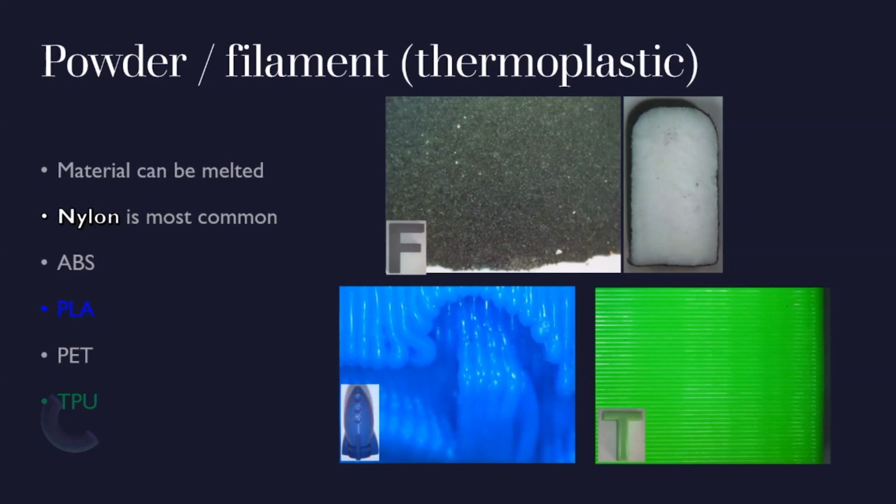Similar in process and properties to ABS is PLA, which is short for polylactic acid. Its key characteristics are that it is cheap, easy to print, and considered a renewable bioplastic that can be composted in high temperatures. However, long-term stability of the material is not fully known under museum conditions, and degradation of the PLA could lead to unwanted products. The blue rocket is an example of a PLA object.